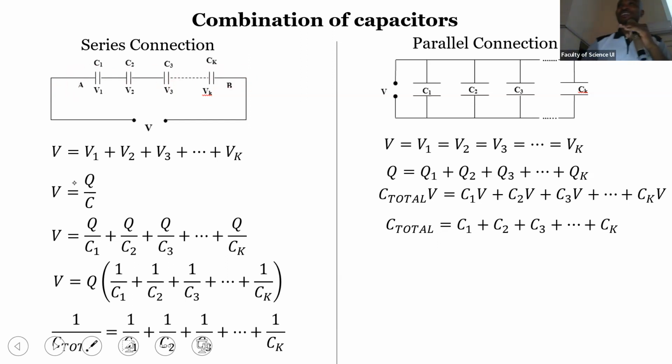And nowadays, we have inverters, where you have a single inverter and you are connecting it to like 4 batteries, when each of them is rated 12 volts. And let's say your inverter is rated also 12 volts, then you should connect all the batteries in parallel.